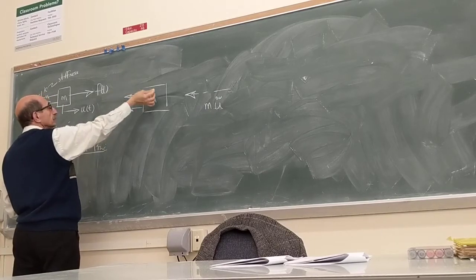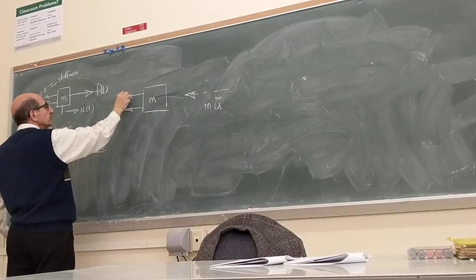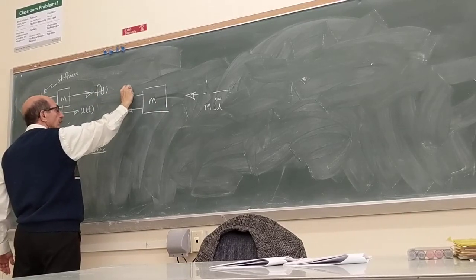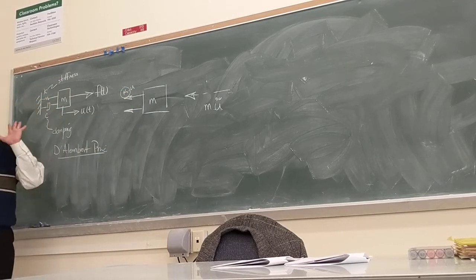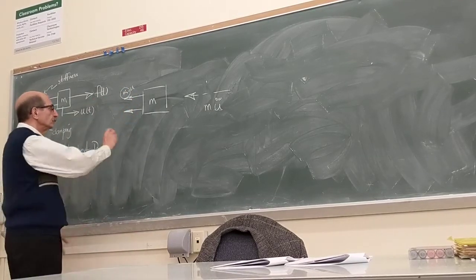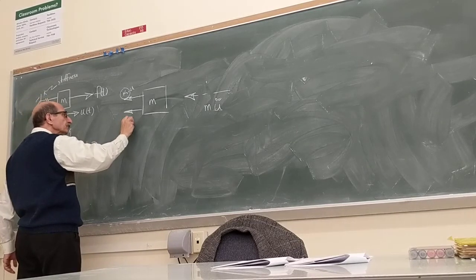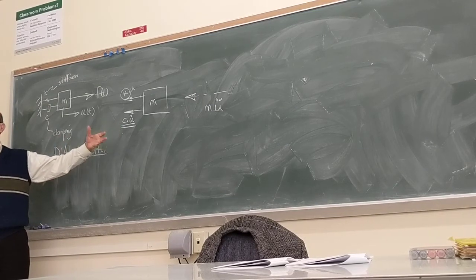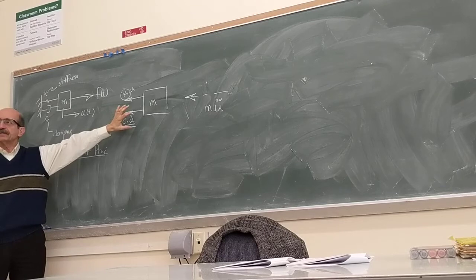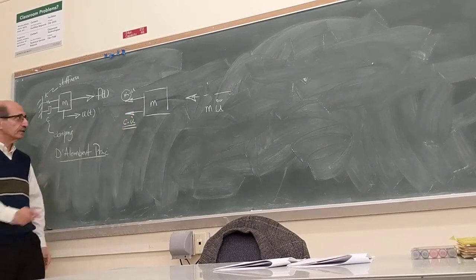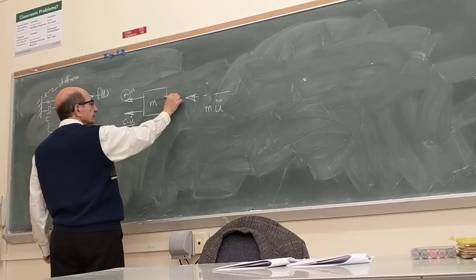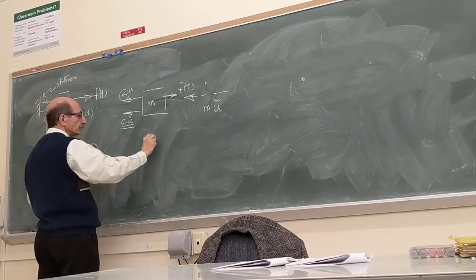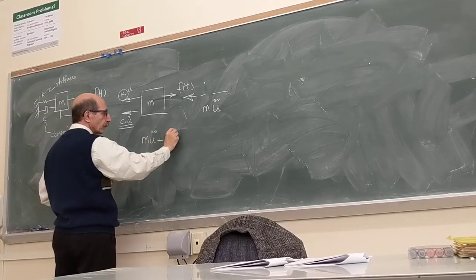So if we set up the free body diagram, here we have a linear force which is proportional to the displacement, the stiffness, which we will talk about later, would be just k times u. This, by definition, we say is c, the damping coefficient, times the velocity. It is not based on any kind of physical derivation, but on assumption. And then, of course, the applied force, and from this free body diagram we set up this equation of motion, right? So that's where we work.